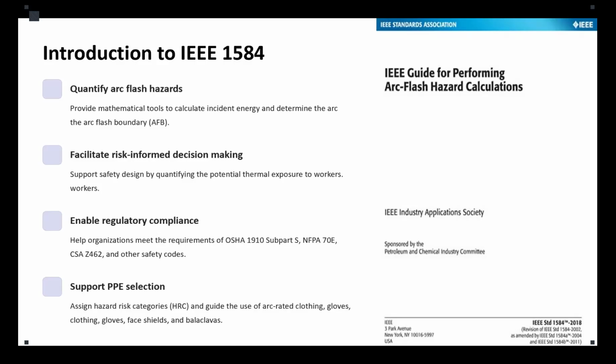These standards all mandate an arc flash risk assessment, and IEEE 1584 is the recognized method for performing those assessments. So it is the benchmark that regulators expect us to use for calculating the risk of an arc flash.